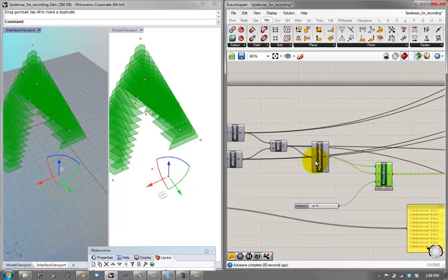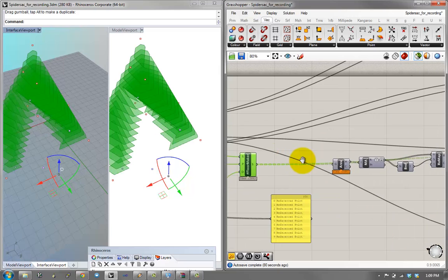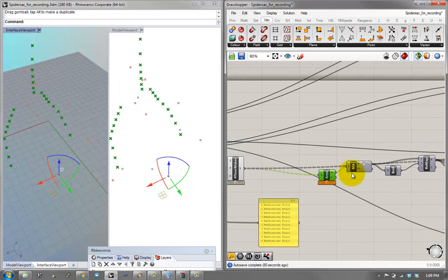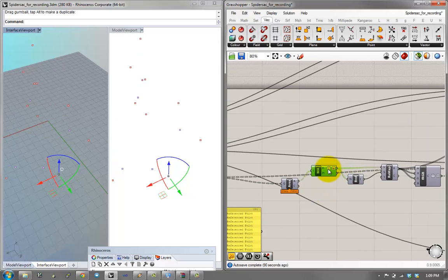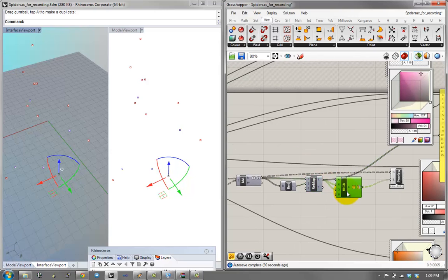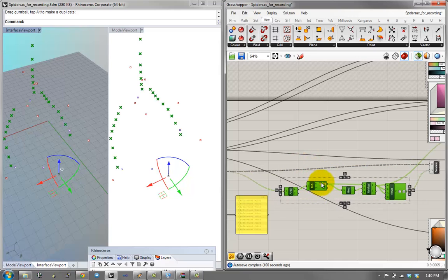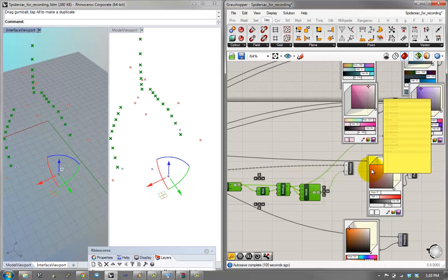And this would be incredibly convenient conceptually because I can say, oh, well, I got the lowest point, I'm just making floors. The same goes for here. I have the area, I'm adding the areas together per floor, I'm getting the bounds of each floor's ranges so I can remap it to 0 to 1, so I'm getting a color. So I could say this is actually a process of getting the geometry and offering up a color.